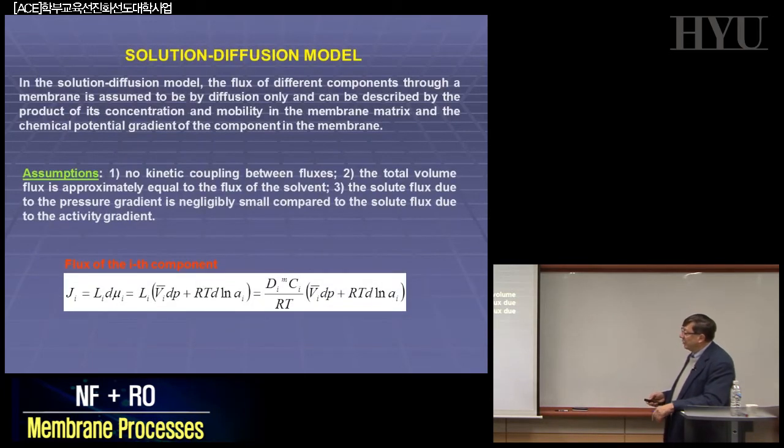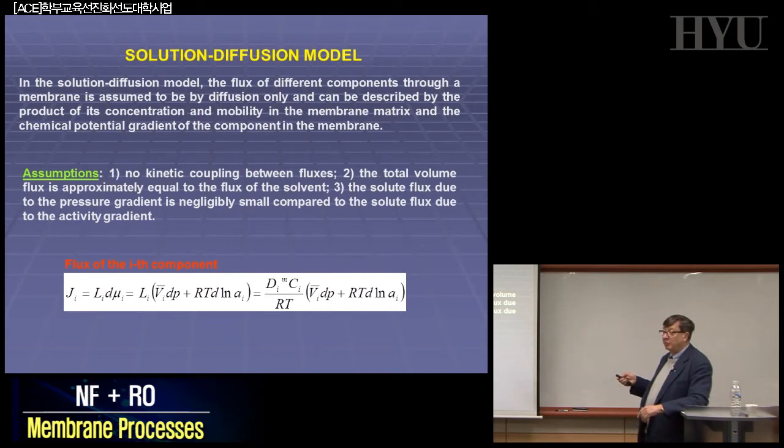In this case, if you want to understand what is happening, there is still discussion about the effect of porosity in these membranes. But to make life easier, we don't need to talk about porosity here. We have to talk about a new mechanism we call the solubility-diffusivity model. So in this case, it has nothing to do with microfiltration or ultrafiltration, where the mechanism was just convection, viscous flow across the pores of your membranes. Nothing to do here with charge effect, as in nanofiltration, but just solubility and diffusivity.